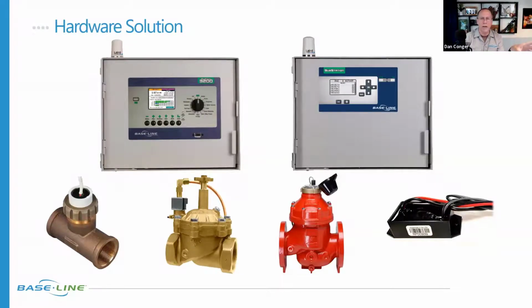So then the next device they used was flow meters, or flow sensors, to measure flow at various points, because we need to know how water is moving through the system. They had 8 flow meters and 8 master valves. Some of those they combine together into hydrometers, but either way you look at it, we've got an option of 8 flow devices and 8 master valves. They currently don't have any pressure sensing on the system, but they have an option for another 8 pressure sensors. Combining those together is what we call a control point.